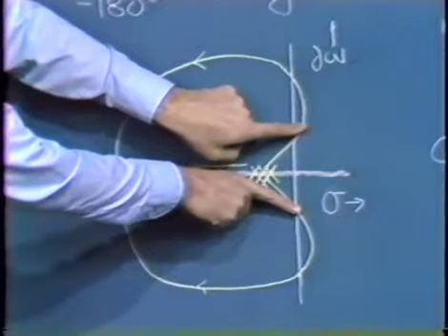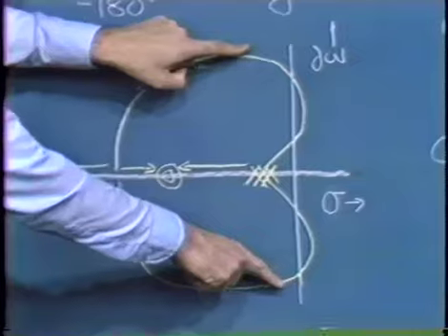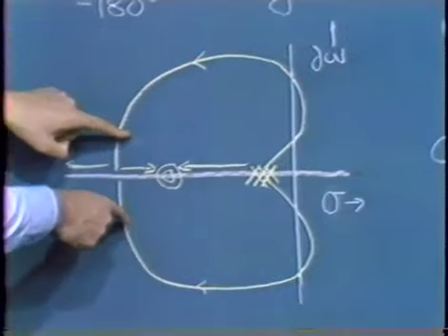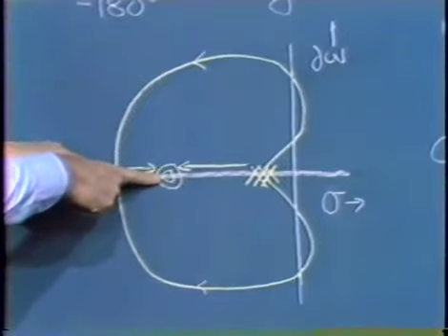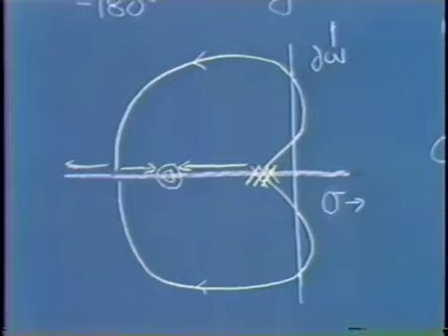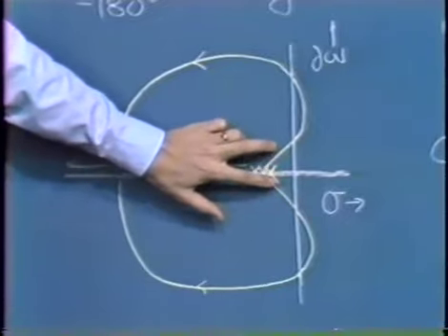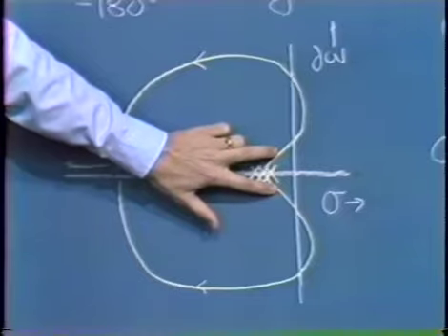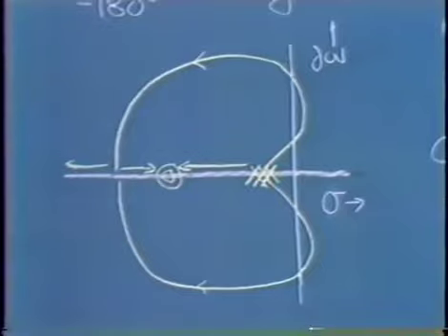We recognize that for larger values of the A naught F naught product, the branches circle around, eventually meet on the real axis. One of the branches heads toward one of the zeros at this location. The other branch heads off along the negative real axis. So if we looked at the stability of this sort of a system, we'd find that it was stable in an absolute sense for small values of the A naught F naught product. All 3 of the closed loop poles would lie in the left half plane.